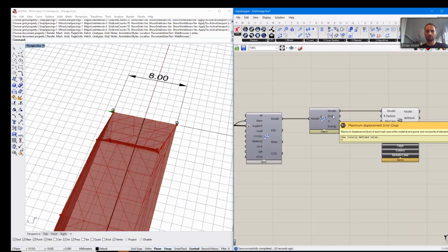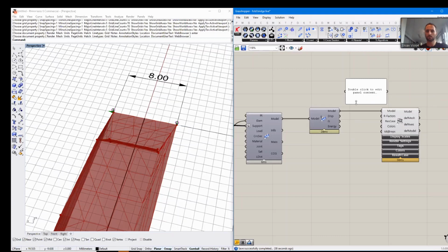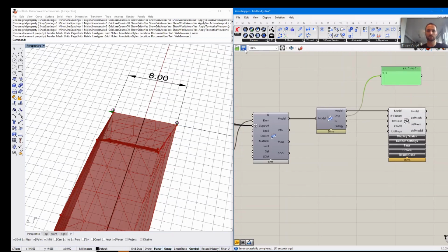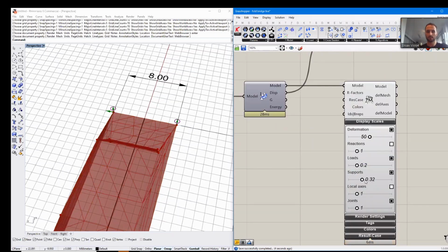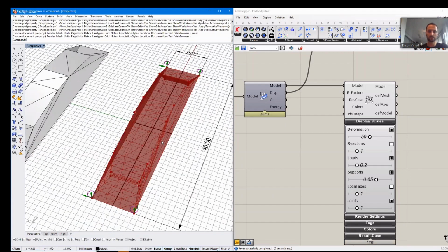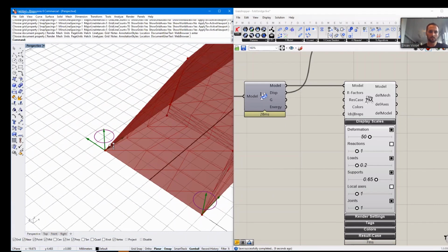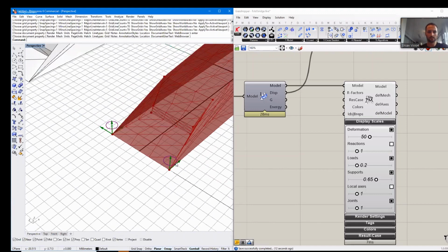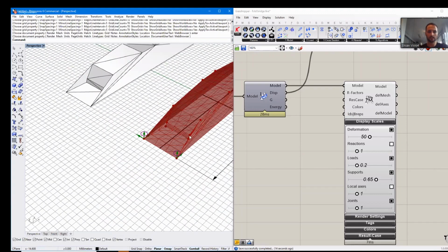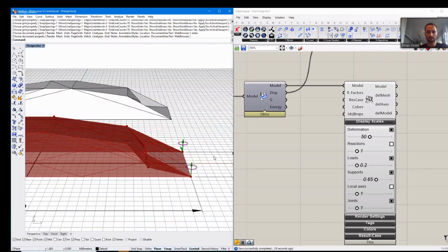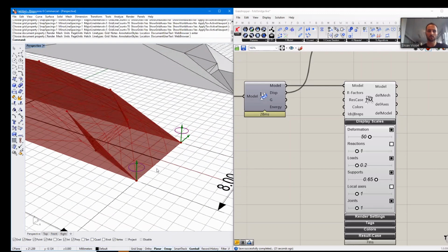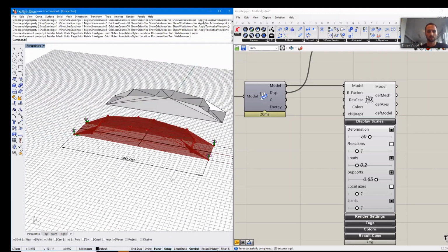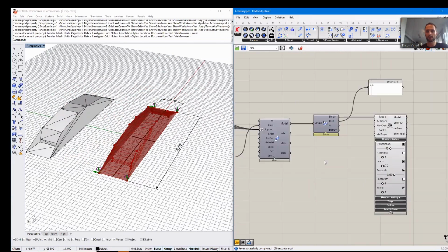Right now we could show what the analyzed component gives us, which is the displacement. We're not having any displacement right now. We haven't defined any loads, but we can look at the structure already. As said, now we can look at the support conditions also. At this point, we have fixed in all 3 directions. This one is just fixed in 2, so we can slide in the Y. And the other side can slide in the long direction of the bridge in general. And one of them is fixed in the transverse direction, the other not. So this we can already look at.